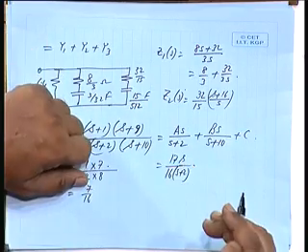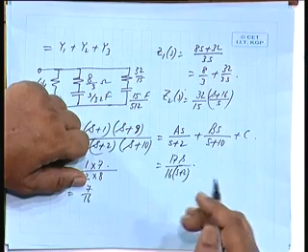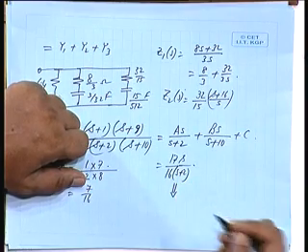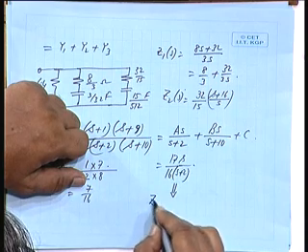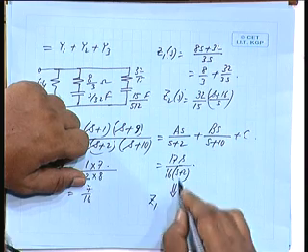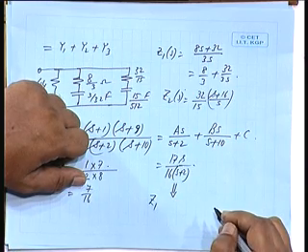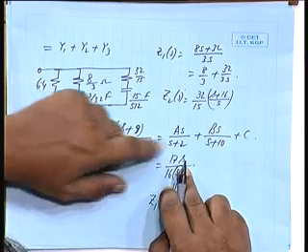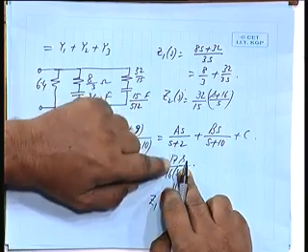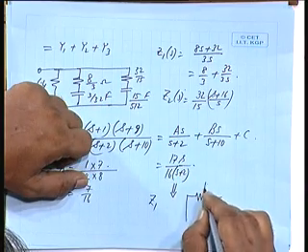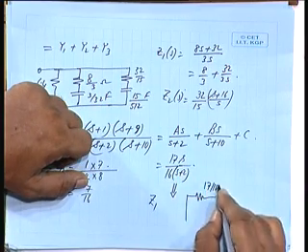Suppose this is an impedance function. What would be the impedance elements? Suppose this is an impedance function. We start with this as Z1. If I make s tending to infinity, this will go to 17 by 16, s will get cancelled, 17 by 16 ohms resistance, is it not?